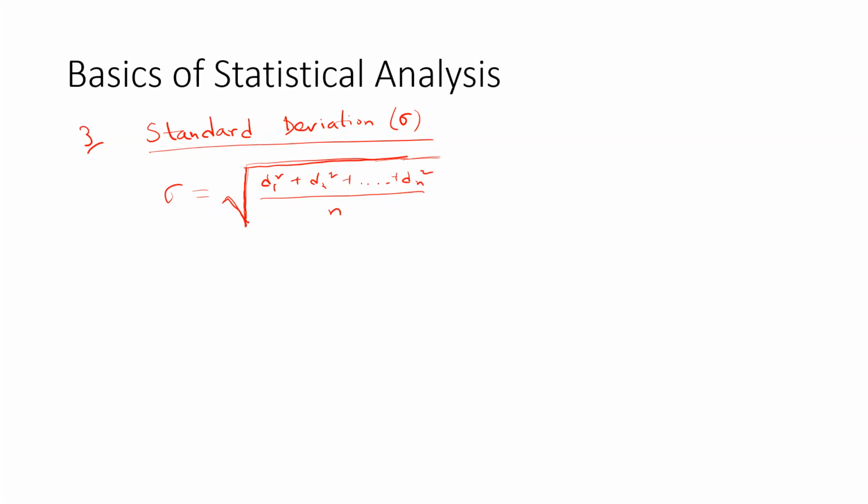Now once you have calculated the overall standard deviation, you don't have to repetitively calculate the deviation each time, because after you know that for a particular instrument this is the possible standard deviation, then when you again measure a particular data, you can already suggest that using this instrument this could be the possible standard deviation.